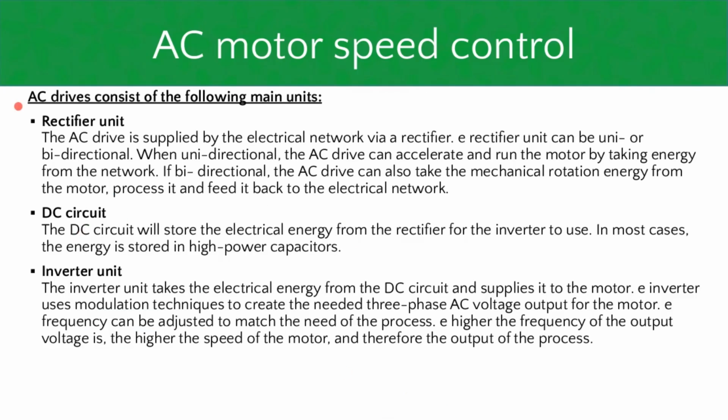Okay, so if you take a look at an AC drive, an AC drive is essentially an inverter system. You're going to have a rectifier that takes your 50 hertz input AC and changes it into DC. You can also use it to generate power in things like regenerative braking. I see I made a typo here myself. It needs to be the rectifier. So you can also use that rectifier unit to push power back into your supply when you use things like regenerative braking. So that's actually also a plus there.